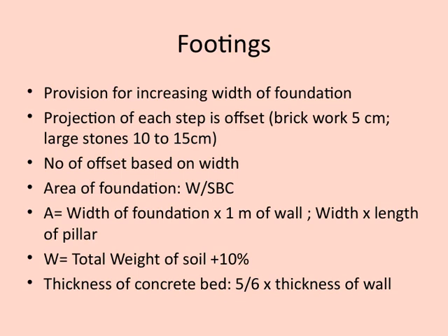Now, let's take a closer look at footings. One key aspect is providing for an increasing width of the foundation, which helps distribute the load more effectively and ensures stability. When we project each step of the footing, it's important to offset it slightly, about 5 centimeters for brickwork and between 10 to 15 centimeters for large stones. This offset is essential to prevent undue pressure and to create a proper stepping pattern. The number of these offsets depends on the width of the footing itself, so wider footings typically require more offsets to maintain stability.